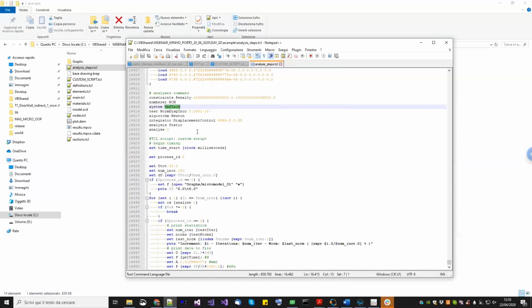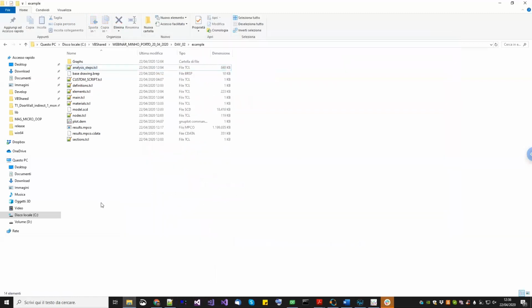The second problem is that since OpenSees needs to send different parts of the model to different processes, it calls an internal method of each element and each material that needs to send their data to the other process. And I've seen that in OpenSees, many materials and many elements are not implementing that method. Why? Because probably the developer who was developing that material was not interested in parallel processing, so he didn't put the code necessary there. So the main problem with OpenSeesSP is that you don't know if you can run your model in parallel, basically. The nice thing about OpenSeesMP is that you can run everything in parallel.